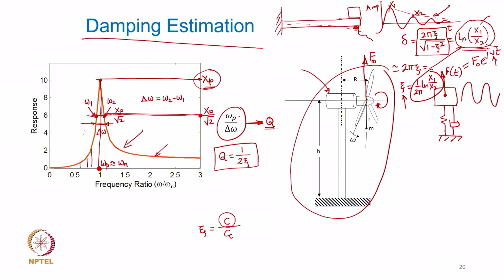If you get the plot properly and accurately measured, it is possible to get an estimate of the damping ratio using the concept of quality factor. So, it is going to be 1 upon 2 into q, where q, it is possible to show, is the ratio of the peak amplitude frequency over the frequency bandwidth. That frequency bandwidth is something which we are going to discuss.